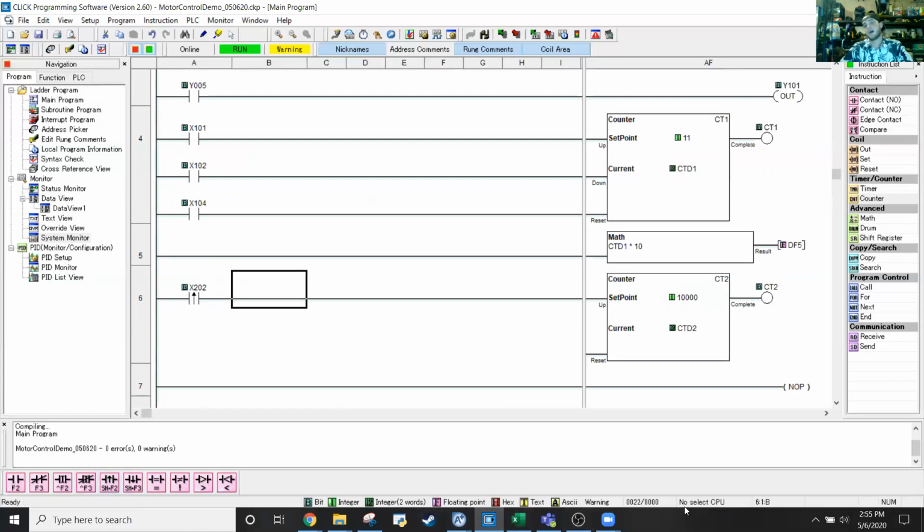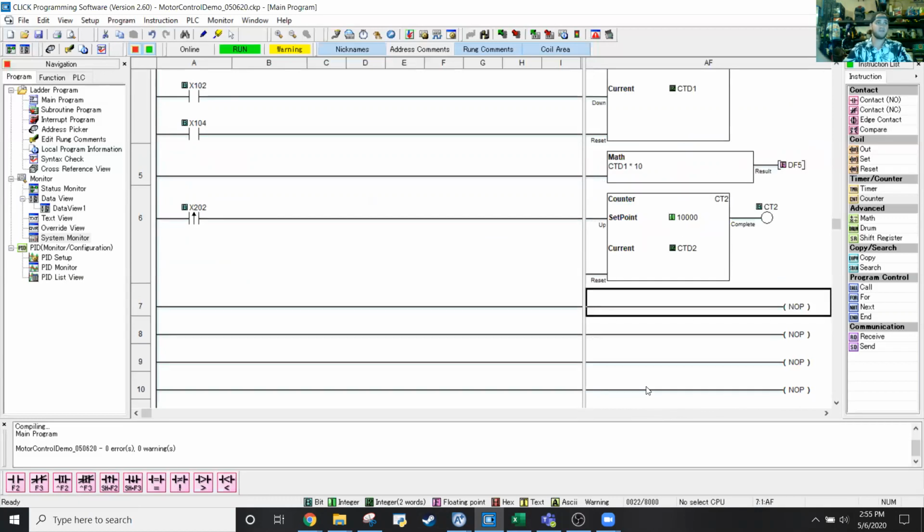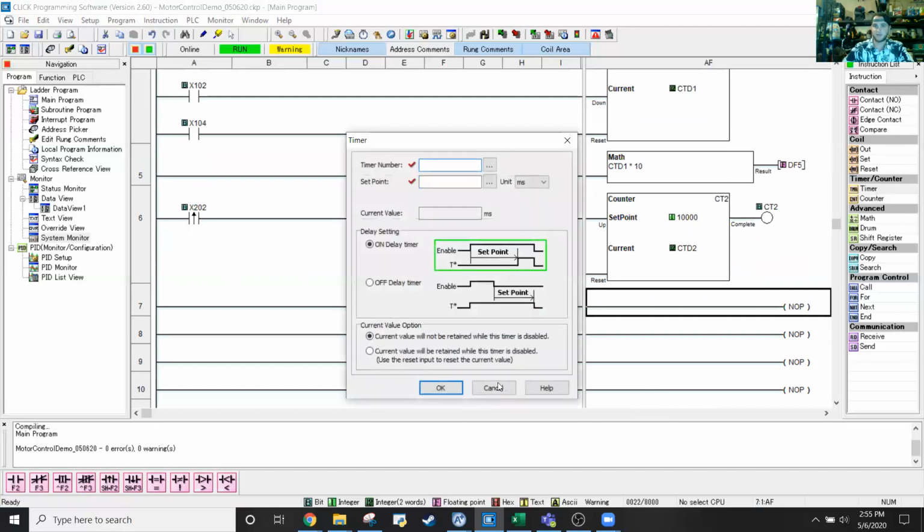Okay. So now you have the ability to count up, right? That'll let you basically start accumulating counts of how many times my motor has spun. But that's not in and of itself enough to figure out how fast my motor's spinning, right? Because there's a time component to motor speed. It's revolutions per unit time. Usually you count that in RPM, revolutions per minute. So the other part we're going to need is a timer, which is just another block in here.